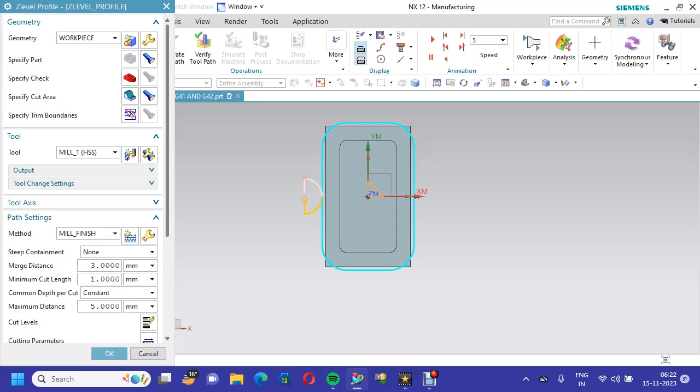It will travel here, then it will go to here and depart the cutter. Then it will come to center, and approach this way. So each and every time the cutter is in this position, it has to approach, then run around the profile, and after that go back to departure, then go to center.